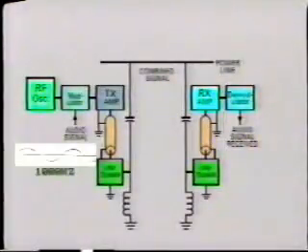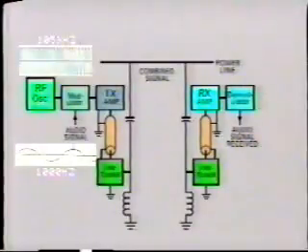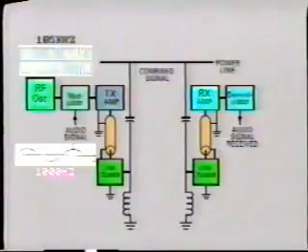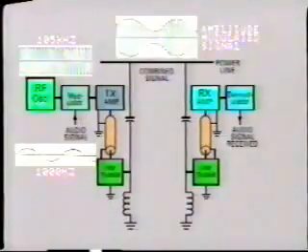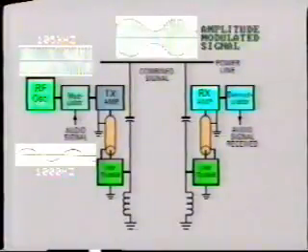Suppose, for example, we wish to transmit a constant 1,000 hertz signal, perhaps for alarm purposes. This audio signal is superimposed on the high-frequency carrier signal, say 105 kilohertz, and modifies the amplitude of its wave. This is known logically as amplitude modulation, AM.